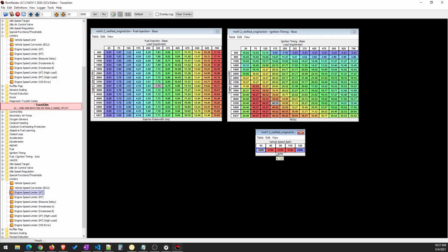The other cool thing you could do is while you're quote unquote two-stepping, you can probably shoot some flames if you modify these two values as well. So again, going back to your fuel injection base map, whatever you set this value to, so if you come over here to 28 to 31, 100 RPM, if you add a bunch of fuel here, let's say like 10, 20% to this value, you can dump a whole bunch of fuel.